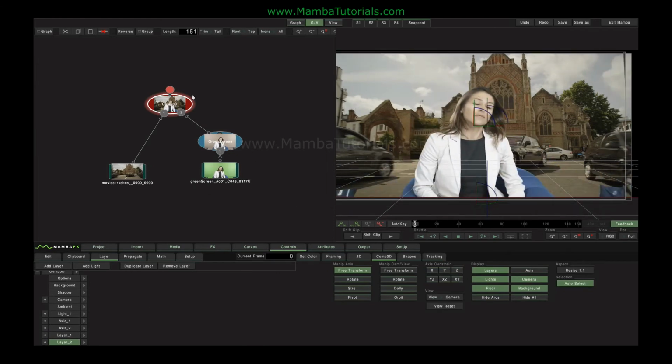Normally when you add layers, these folders will add on their own. But if you need to add layers manually, the button's here, likewise to remove or to duplicate a layer. Duplicate layer will simply take whatever you've got highlighted and create a duplicate folder with all the same parameters. It won't actually duplicate what's going on in the nodes, it's just a parameter thing.